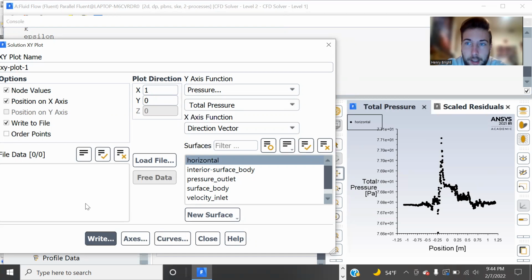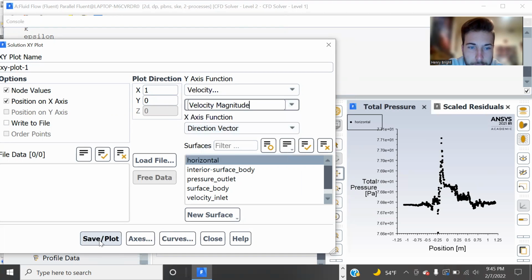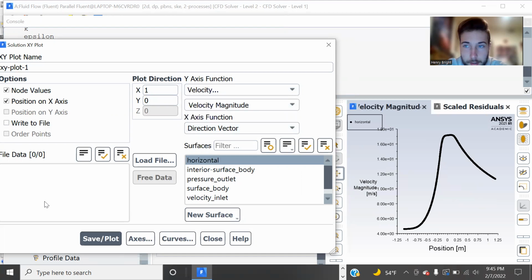And if you change the scale of it, you'll see it's just a horizontal line, which is exactly what we would expect. So that's good to see. And then of course, velocity is going to be basically like our dynamic pressure, because they're just related. It's incompressible flow, density is constant, so dynamic pressure is just variable based on velocity. So that's exactly the relationship we would look for.